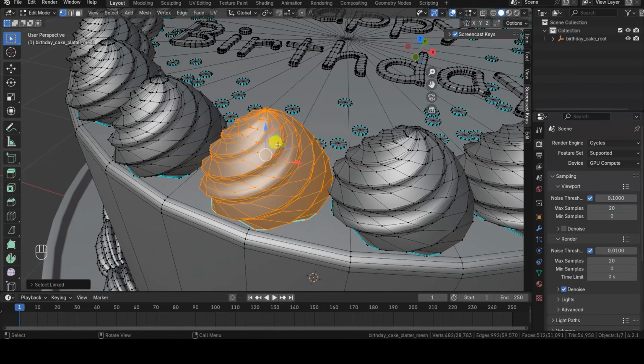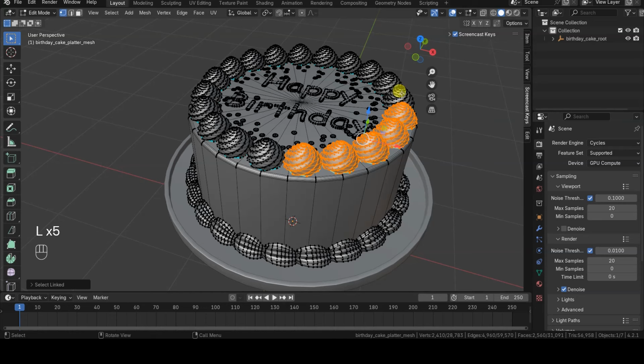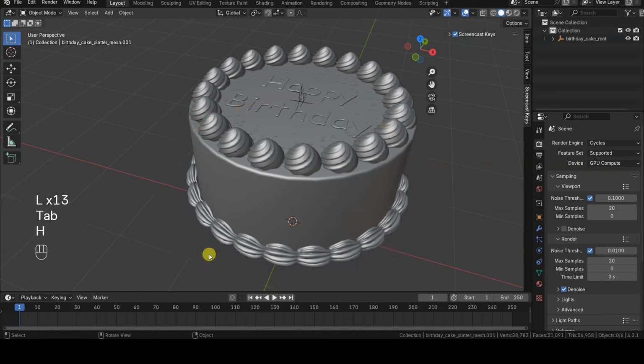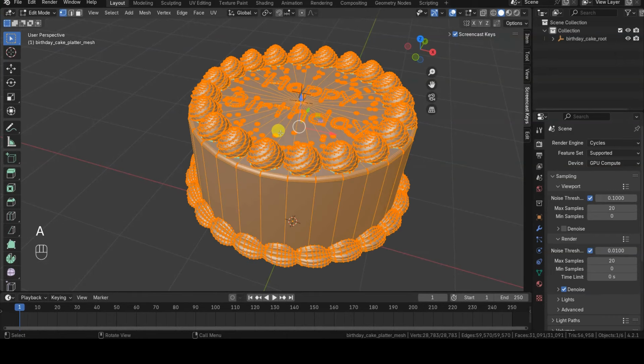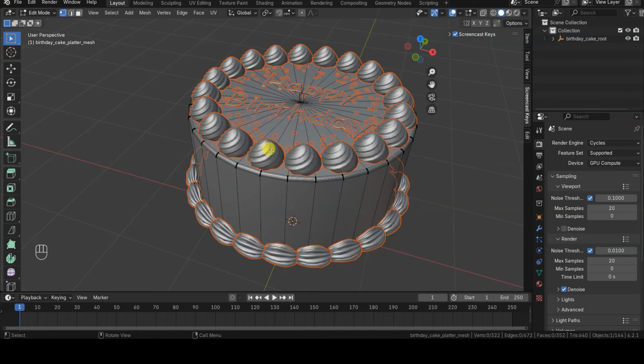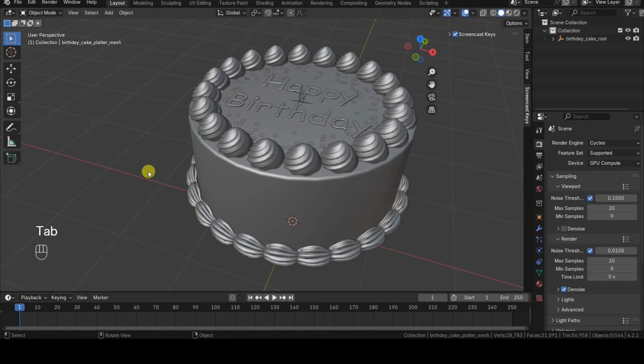In the 3D model I use for the examples, there are several parts not connected to the main model, and it could be useful to detach them entirely from the original to modify or replace them separately. I am selecting individual islands by pressing the L key, which is the shortcut for linked, while the mouse cursor is over each island. The operator acts only on selected parts, but in this case, I can select all the geometry and apply separate by loose parts, resulting in many new objects.